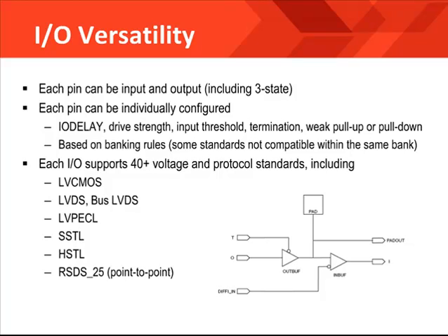The SelectIO feature allows direct connection of the FPGA pin to external signals of varied voltages and thresholds. This optimizes the speed-noise trade-off and saves you from having to place interface components onto your board. All the dedicated interface logic already exists and can be selected on a pin-by-pin basis. However, note that to mix different I/O standards into the same I/O bank, you must be aware of the I/O banking rules. These rules apply because each I/O bank shares the power pins for each of the input and output pins in the bank. Specifically, the VREF powers the input circuitry and the VCCIO pin powers the output circuitry. So whichever I/O standard you group into each I/O bank, make certain that the input pins have the same VREF and the output pins have the same VCCIO. Now, this is easily planned with the PlanAhead utility that's included with the ISE design suite.